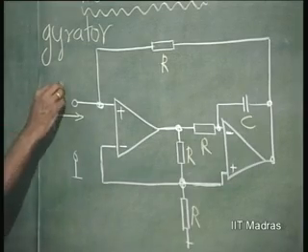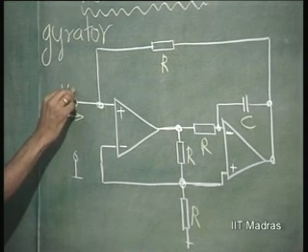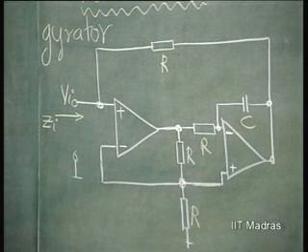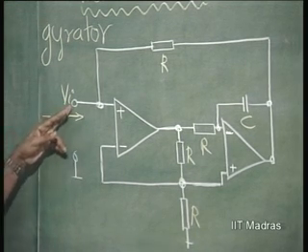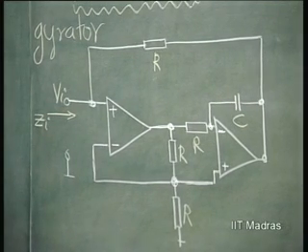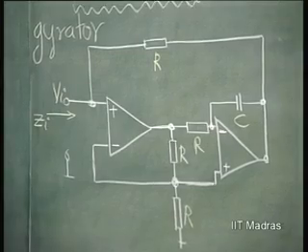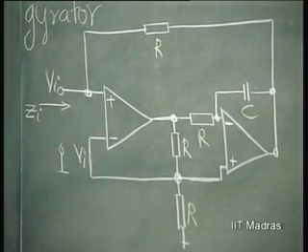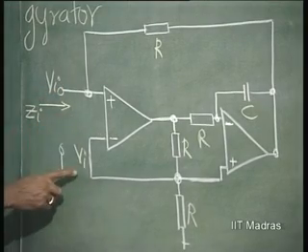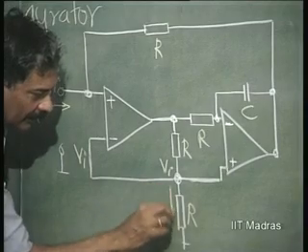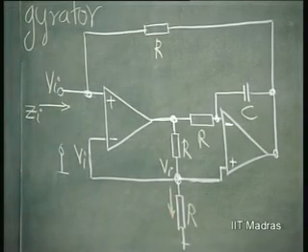So, let us suppose that this is Vi. I am going to analyze this circuit and we will see how to analyze therefore op amp circuit in a very simple manner. If this is Vi, if this is a circuit which is supposed to work with negative feedback, then this has to be Vi. This we said null. If this is Vi, this has to be Vi, and if this is so, this is Vi, and the current in this is Vi by R.